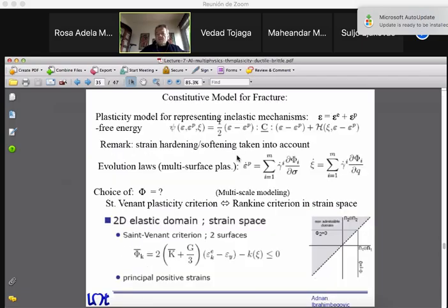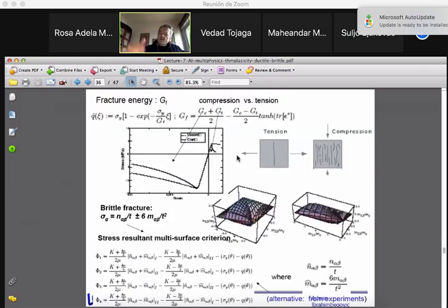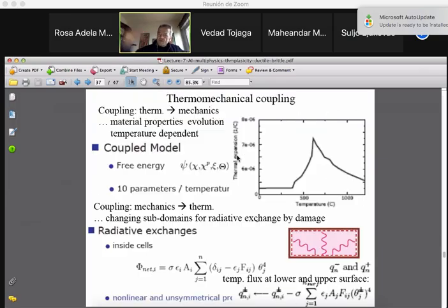you have to capture this propagation of heat flux from the heated side exposed to fire to the side exposed to ambient temperature. In this propagation, heat goes into these alveoli, these empty spaces sitting inside the brick. For this, you need computation of radiative exchange, which is typical, like the sun sending heat to Earth. It's known that this is proportional to the temperature to the power of 4. So you need to equilibrate these fluxes over the 4 facets of the hole.